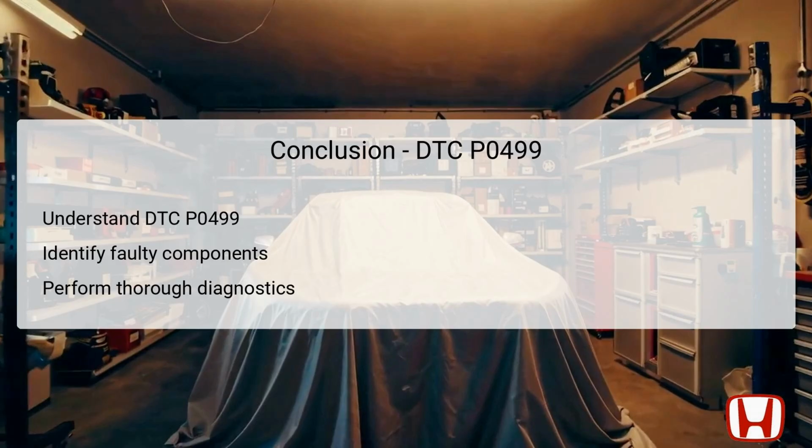By identifying faulty components, like the EVAP canister vent shut valve, and recognizing possible wiring issues, technicians can navigate the troubleshooting process effectively. Performing thorough diagnostics using HDS tools ensures accurate identification of problems, and various repair strategies can be employed based on the findings.